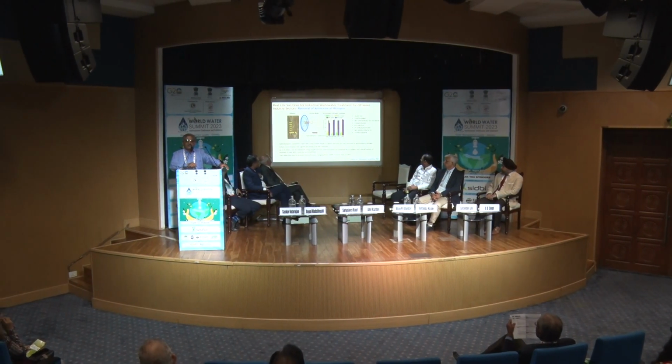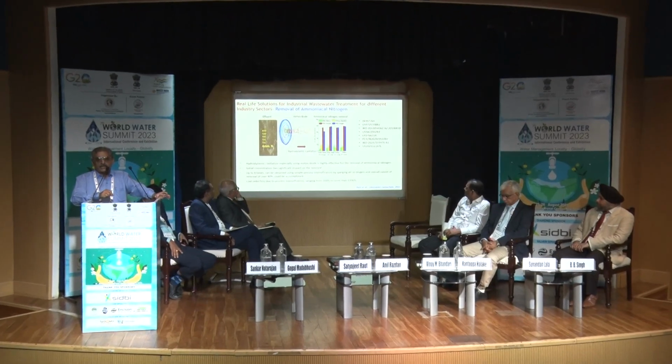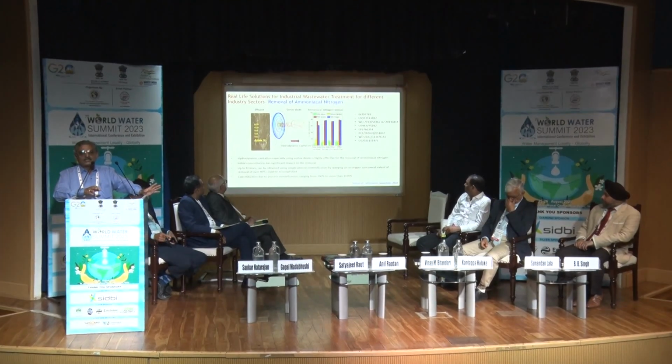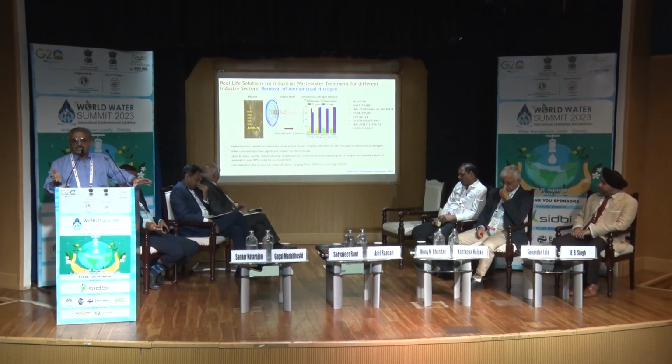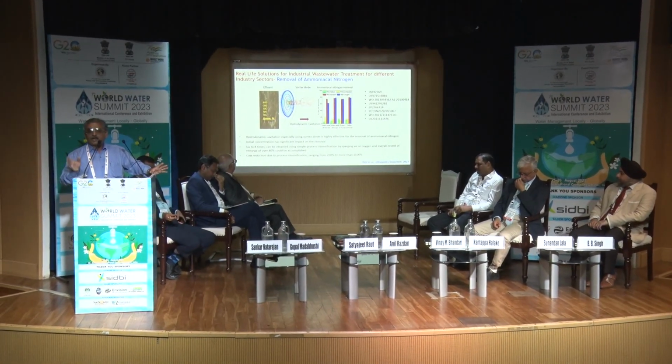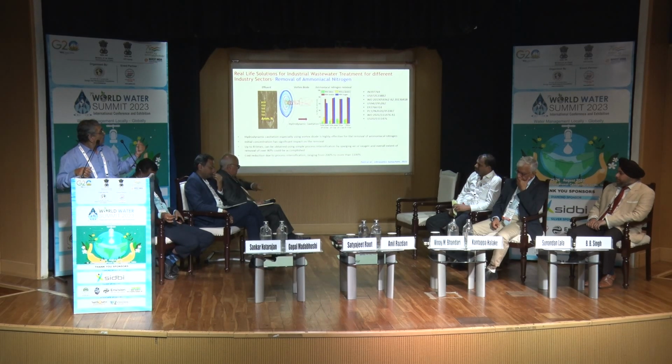Now, apart from the pharmaceutical industry sector, another sector which requires a lot of attention is the dye industry and many other bioprocessing industries, where ammoniacal nitrogen is the main culprit. COD is not a problem because there it is all biologically degradable components, so you have biological digesters working very fine, but ammoniacal nitrogen is a major problem. Close to 700 ppm ammoniacal nitrogen you get in wastewaters, and you have a requirement of below 30 ppm. So this technology is also quite useful for removing ammoniacal nitrogen from wastewaters. Next one.